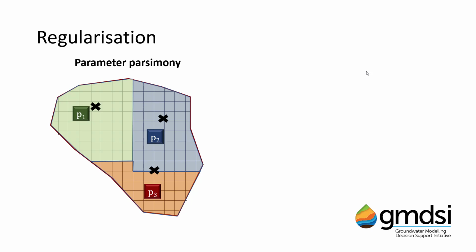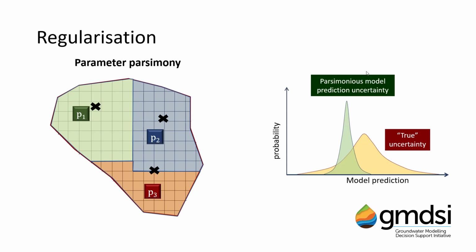Adding piecewise constant zones, for example, creates boundaries where properties change abruptly and do not follow geologically realistic patterns. These zones will have been delineated based on subjective choices by the modeler, and too few zones decrease the ability of observations to actually inform parameter estimation, which, as we've said, can result in model prediction bias. Such parameterization schemes may result in good fits with observed data. However, their parameter values are effectively very coarse surrogates for the complexity of the real world. Perhaps most importantly, by using few parameters, predictive uncertainty is often underrepresented. Fortunately, that type of approach is now a thing of the past.